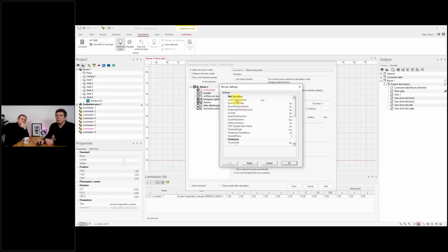One of the really useful things here is, for example, the luminaire subdivision. This is how fine it is if you have a linear luminaire, a longer luminaire. In order to provide you a good impression of the light output, we separate the linear luminaire into smaller pieces and put part of the energy into single LDCs for each. The more, the better is the visual impression, especially if you put a linear luminaire straight to a wall,